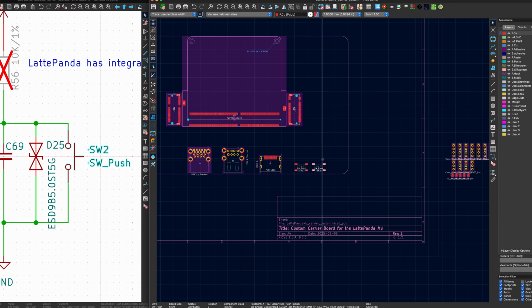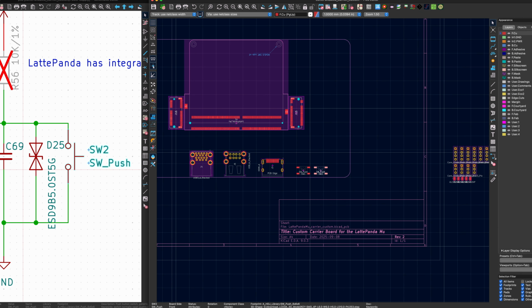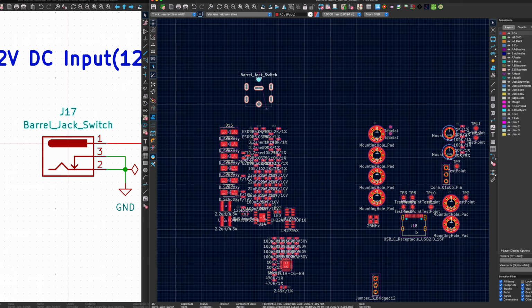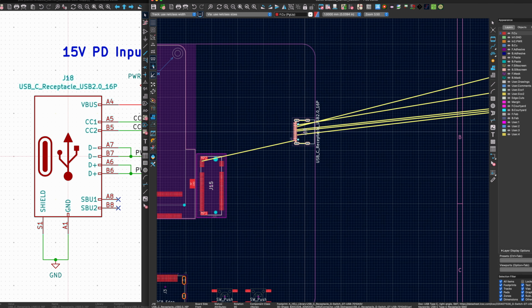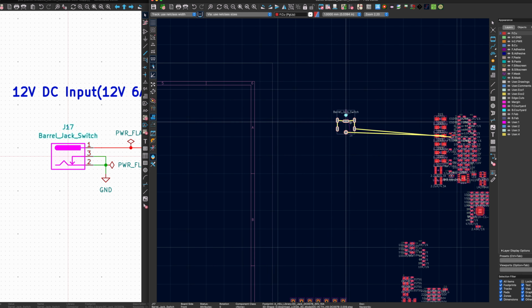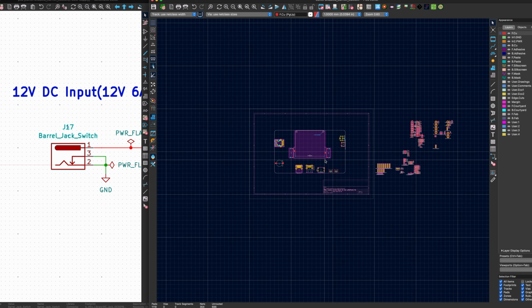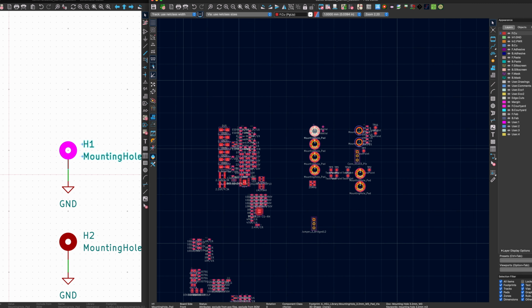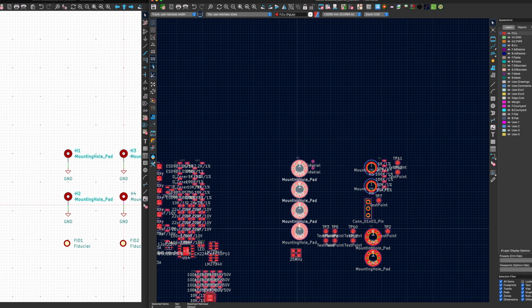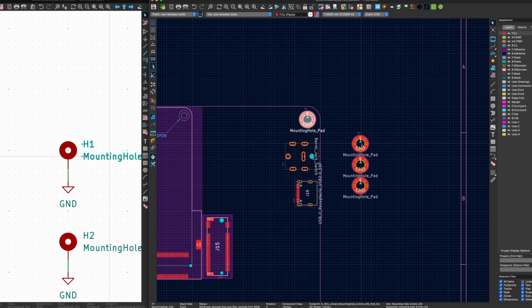You learn how to handle USB 3.0, Ethernet, and HDMI routing using KiCad's high-speed routing tools, including differential pair tuning and visual length equalization. And throughout all this, you'll build both theoretical understanding and hands-on proficiency in the most challenging aspects of modern PCB design.